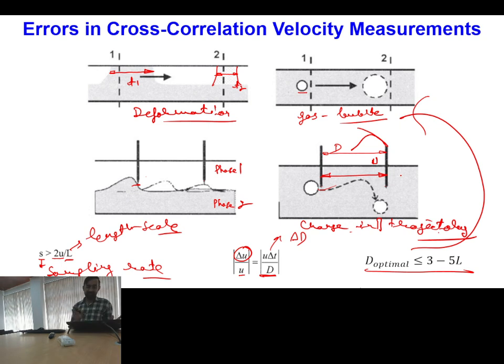Okay, majority of the time cross correlation cannot give you the idea of the total bubble velocity, but it can tell you about the upstream interface velocity. That is something which people majority of the time try to calculate. Whatever the first point is when the signal has changed, that will give you the upstream interface velocity.